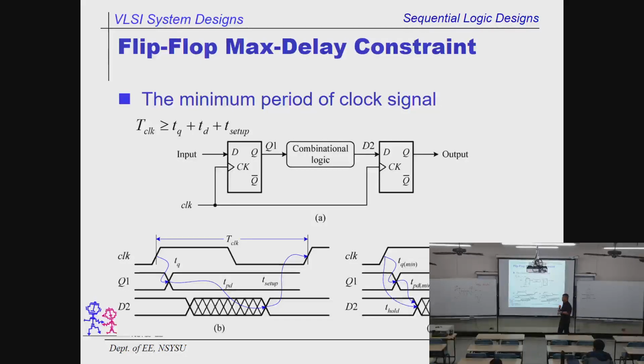So from time to time, a lot of students told me that their adder output is wrong. I told them to do one thing: slow down the clock. Make the period a little bit longer. If your addition is wrong when the clock is fast, but the addition is correct when the clock is slow, that means you violate that rule when the speed is high.